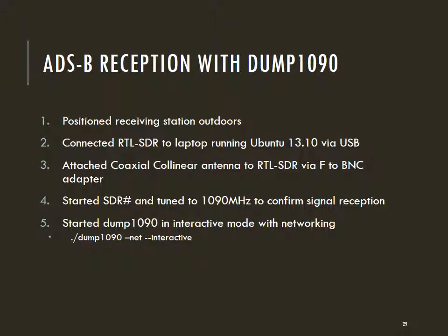These are the basic procedures that we use to receive the ADSB signals using the Dump 1090 application. First, we made sure our listening station was outdoors, away from any kind of buildings, to get away from the shielding and EMI produced by being indoors.